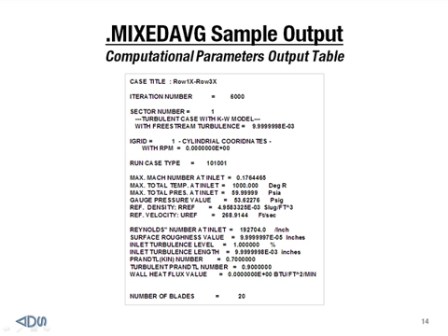And then more importantly, it gives the inlet Reynolds numbers, the surface roughness that was used, the turbulence level of the mainstream flow, the length scale, the molecular Prandtl number, the turbulent Prandtl number, and any heat flux boundary conditions that might have been imposed. And it also plays back the number of airfoils for this particular row. This information helps the user double check his input and what was used for the calculation. So it's kind of a sanity check.